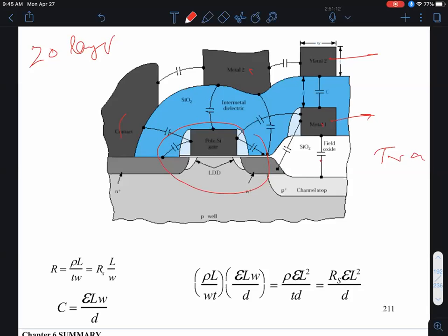Okay, but when you do that, you have to isolate these metal interconnect layer from an underlying metal interconnection layer, and then above that, I'm not showing it, you'd have other layers of dielectric, higher and higher levels of metal interconnection lines. Okay, and then you join them up as needed by so-called contacts, or you may join, say, this metal with this metal. I'm not showing it over here, but you have other connections that you could make. These contacts are called vias, and so on and so forth.